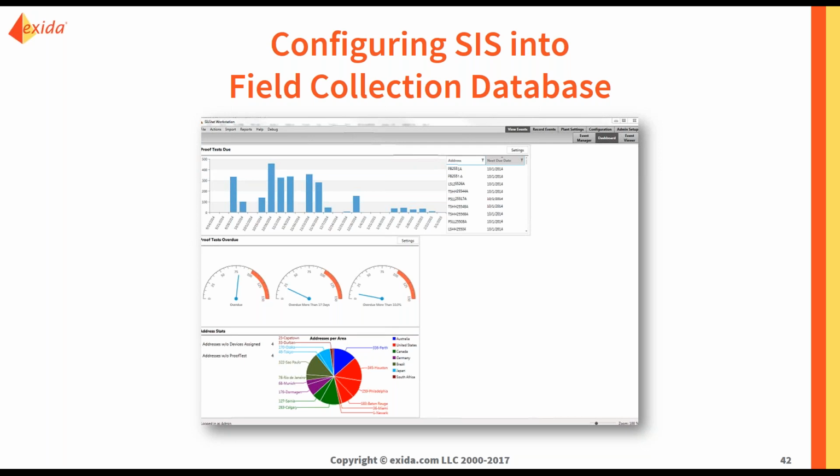You're going to need a database of the proof test procedures, not only what you need to do the proof test, but records that they're all done, any maintenance activities. And then you're going to want to record if there is a demand on your process. If there is a hazard that happens, what independent protection layer guarded against it? All of this is information that you need to record, but how do you do it?